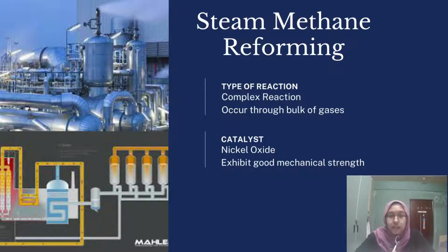For the catalyst, nickel oxide is used for the SMR reaction since it has high reactivity, withstands high temperature, and exhibits good mechanical strength. Due to its high catalytic activity and low price, nickel oxide is selected as the SMR reaction catalyst.